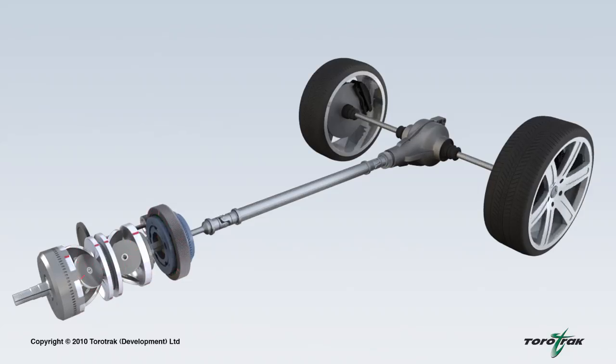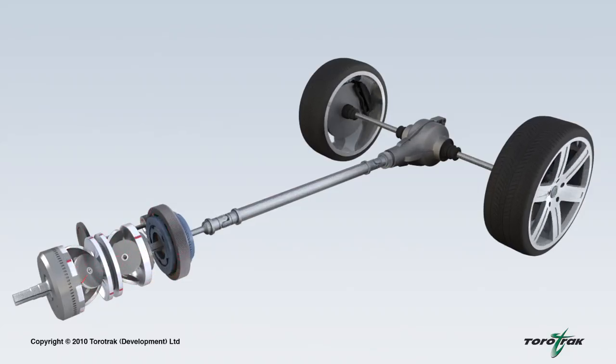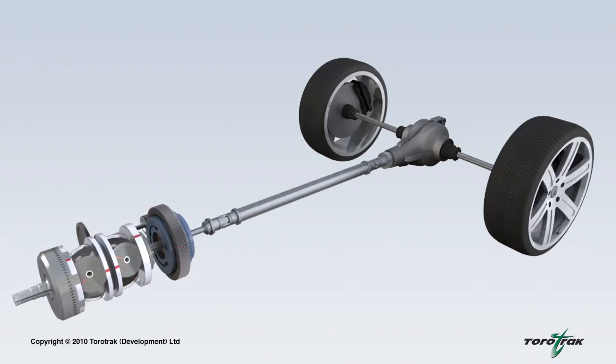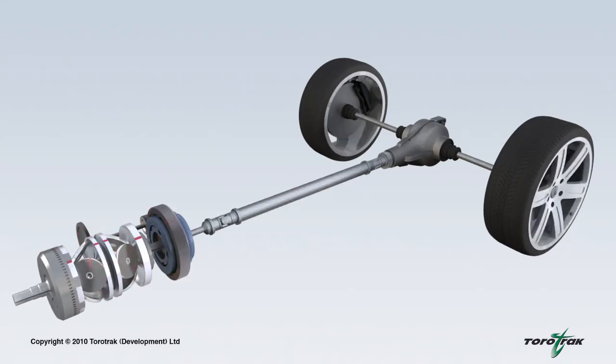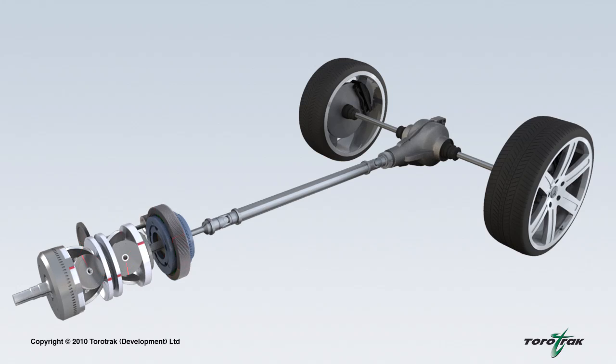The variator ratio determines the driveline ratio, causing the transmission to move seamlessly from full reverse through geared neutral to forwards. As a result, on an infinitely variable transmission, there is no requirement for a starting clutch. Even when the vehicle is stationary, the running engine is mechanically connected to the road wheels. The geared neutral function replaces the requirement for a clutch or torque converter to provide the launch function.